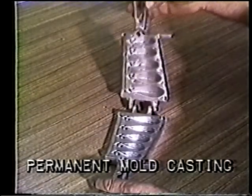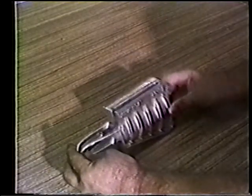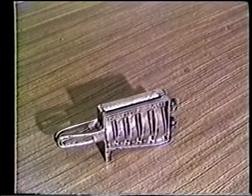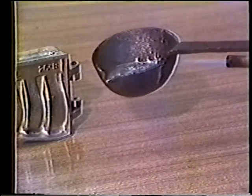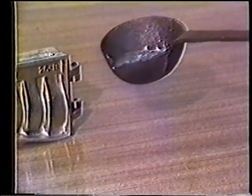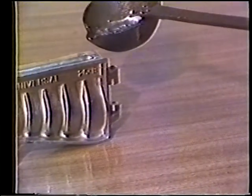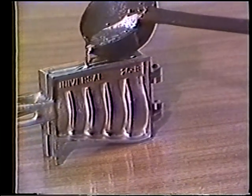Permanent mold casting is a process in which the mold is made from various metals, making it relatively reusable. This process is used less often than investment and sand casting in making aircraft engine parts. As in sand casting, metal is poured into the mold through a system of sprues, runners, and gates under gravity.